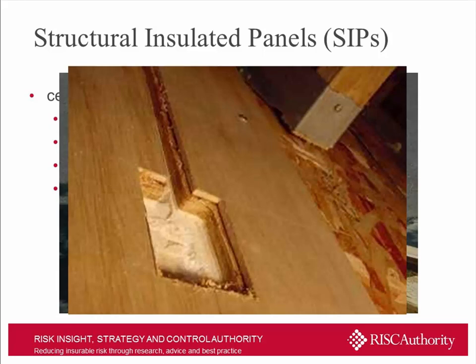But as you can see from that image on the screen, at the moment you start to chase in, exposing the core, or you're creating any kind of void or puncture through the panel, you're obviously going to expose the core to fire, smoke, ignition sources, whatever it might be, and heat, and the potential for fire to spread if those kinds of issues aren't adequately addressed through the use of appropriate fire-stopping materials, insulation and the like, to protect what goes on behind.